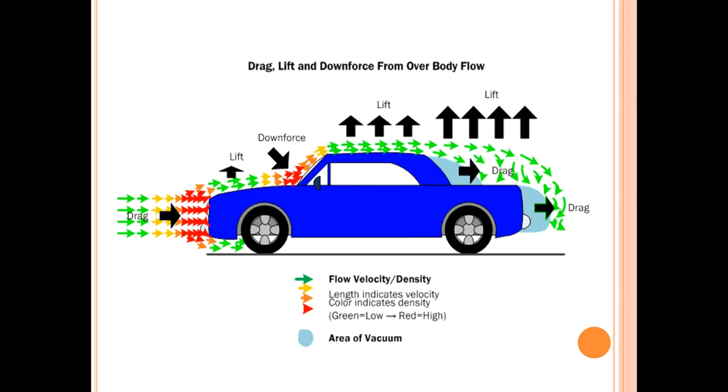So when this low pressure is generated, it means there will be a maximum amount of lift force generated. And to fill this vacuum, the maximum amount of air will be sucked from the front of the vehicle, so it also causes drag. In this way the drag and lift force are acting over the vehicle body.